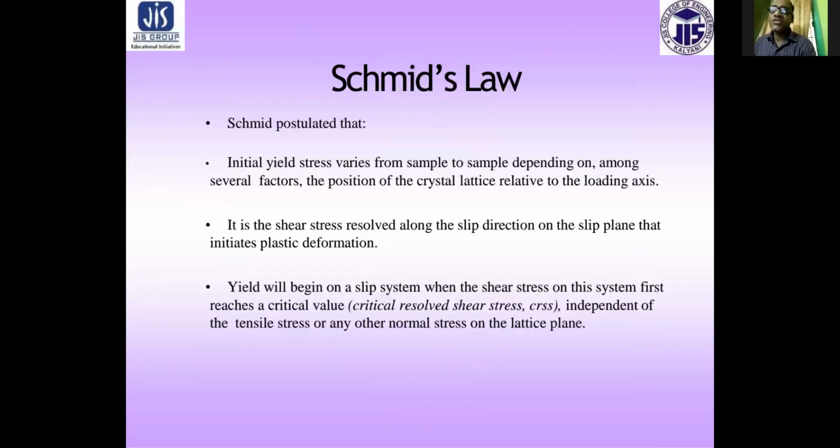Now, what is the Schmid law? It tells that yield stress varies from sample to sample depending on, among several factors, the position of the crystal lattice relative to the loading axis.